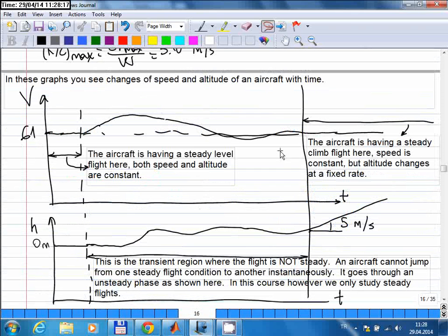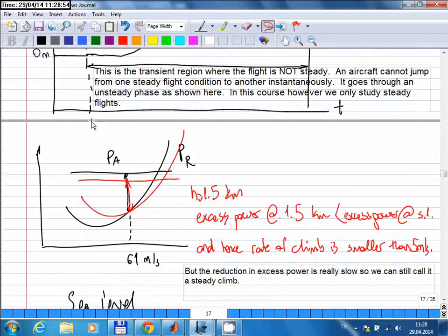Okay, so this is what I was saying here. When things are stationary, when things are steady, we use these equations. But during the times when things are changing, we can't use these plots anymore. So obviously, if you are flying at maximum speed, the pilot can try to climb, right, by pitching up the aircraft, basically. But as soon as he does that, things will start changing, because if he starts a climbing flight, then the speed of the aircraft will be going down, right?